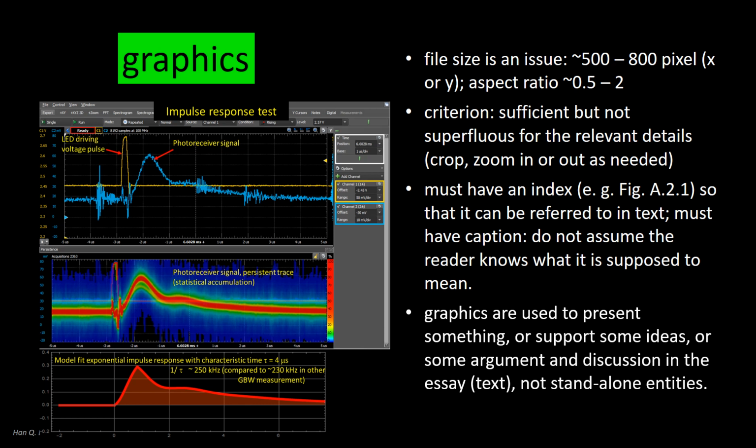This is like a homework being posted, to be due in 2.5 days. But the students take a week just to ramp up reading the homework, and take 3 more weeks to gradually finish the homework. The implication is that this LED photo receiver system, if used in applications such as communications, cannot send 2 successive bits sooner than about 4 microseconds apart, or a data rate more than 250 kilobits per second. Just like for this student system, it is futile to give homework more frequently than once every 4 weeks.